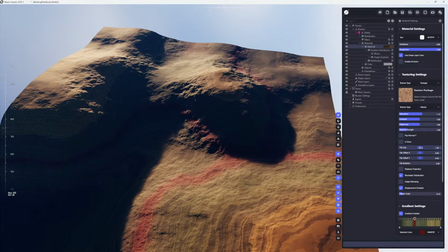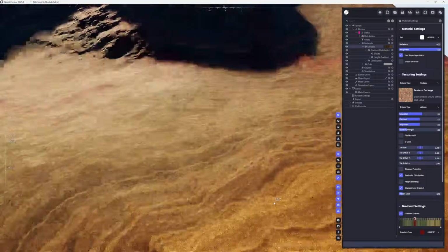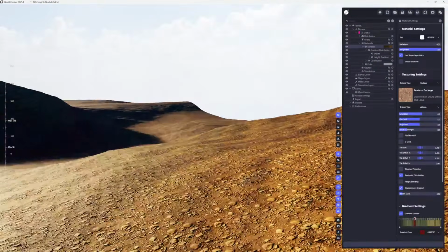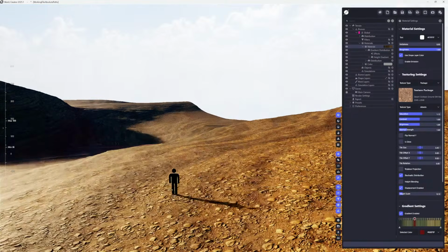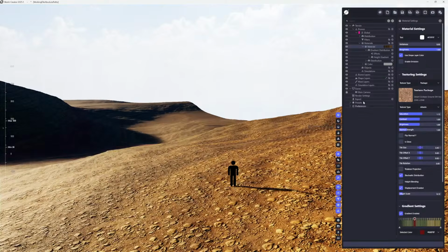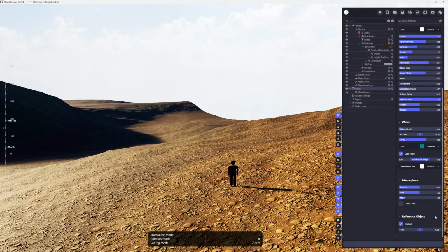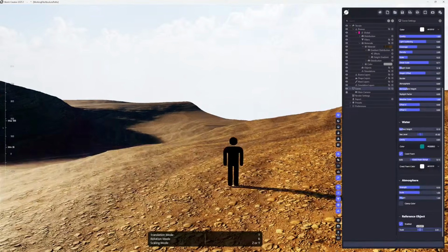Of course, then the tile size, also interesting here. I find it pretty difficult because sometimes you're placing your mannequin. If you ask how to place a mannequin, hover with your mouse over the terrain, press the M key on your keyboard, and then you can place that mannequin. And that mannequin can be adjusted in size. If you go to scene, you can adjust the size here for the mannequin as well.